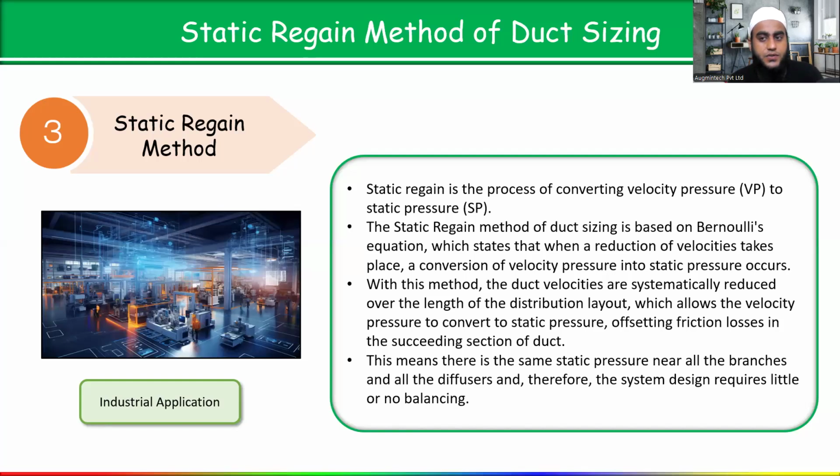And where we have to use the static regain method, generally this method is used for industrial applications where the duct route is long. Okay. So now see, for that, it is written here, everything. Okay, what I have explained. Here you have to remember one thing: if the duct route is long, because in industrial applications, all of you know, we have long duct